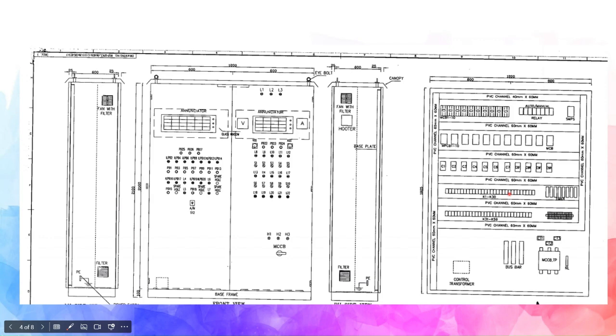When we talk about control panel, we are understanding something like that. Not PCC, not MCC, not PDB, not MLDB. Control panel is something where there is control, where there is power, where there are logics built, maybe some PLCs are there. So in this panel, PLC is not there, the logic is built using the contactor circuits.